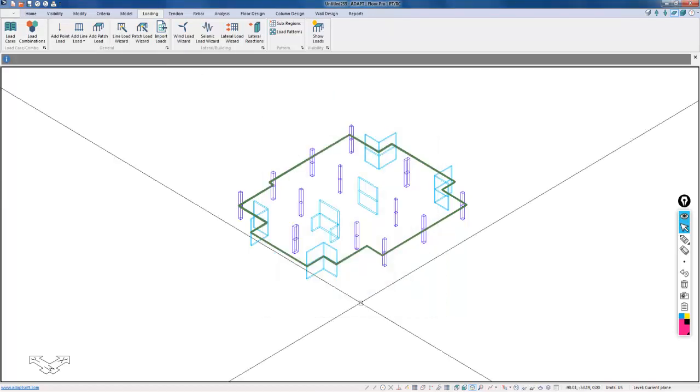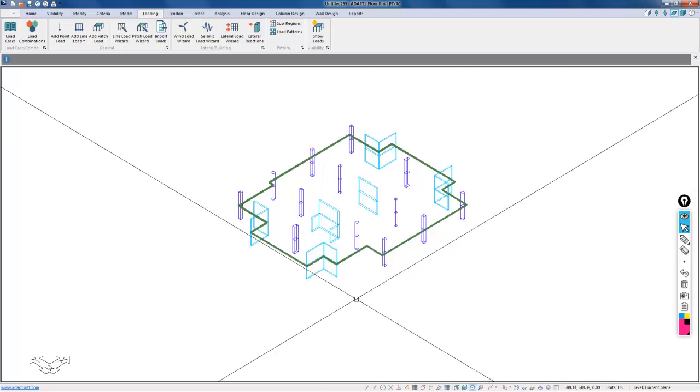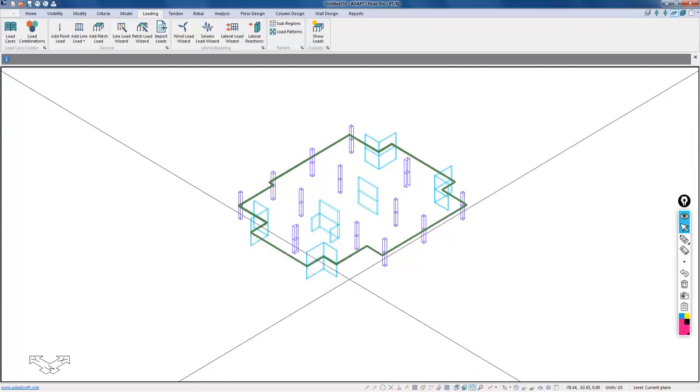we'll select OK. As the user, you can enter as many load cases as you need and name them whatever you'd like. Just avoid using special characters in the load case names like slash, pound sign, percentage, dollar sign, etc. I would just use underscore as a separator. That's a recommended practice for most naming conventions within the program.